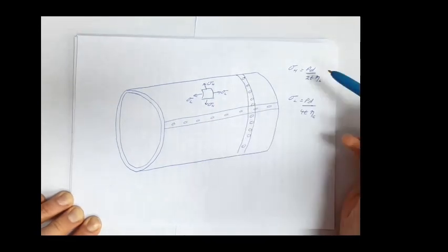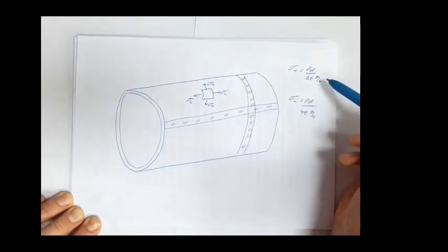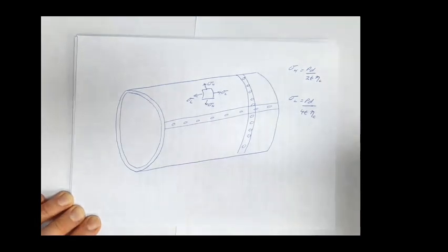Now, these numbers, these efficiencies, will be between 0 and 1. They're based historically on empirical data, so testing, experiments, previous knowledge and experience. You might say, depending on a weld, it might be 0.5 or 0.6, depending on a rivet, it might be whatever.